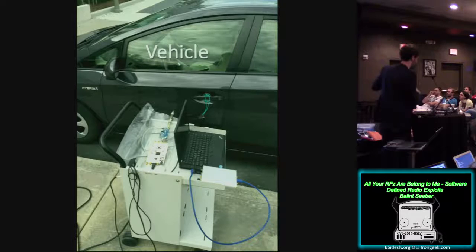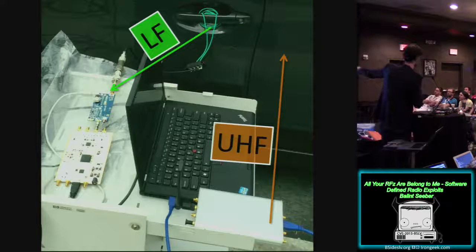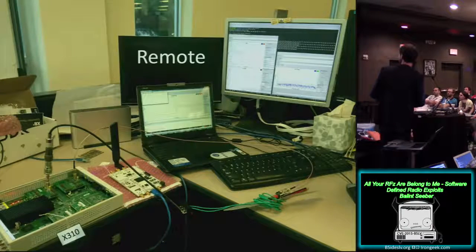So in this case, I wanted to set up a relay to see if you could actually relay it over IP. I had a feeling it wouldn't work for very obvious reasons, but I just wanted to try. So in this case, we're pulling in the low frequency. We've got a Hammond up converter hooked up to a B200, and this B200 is actually going to send back the UHF from somewhere else.